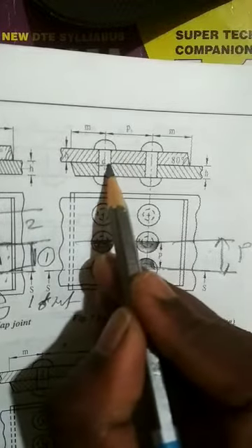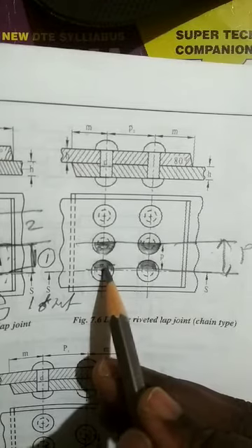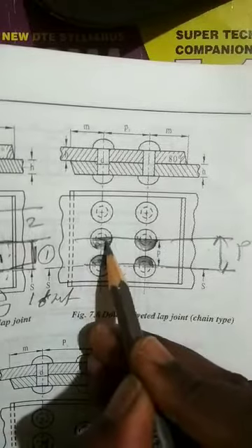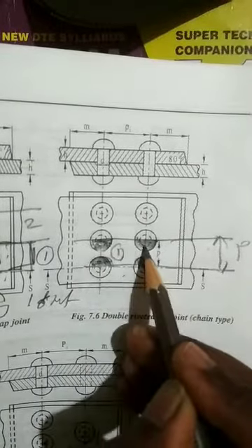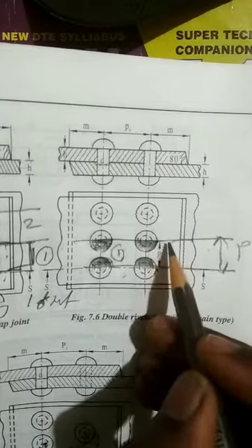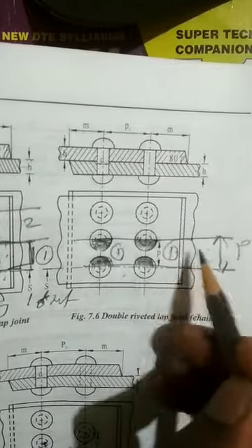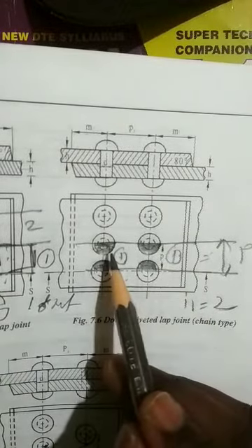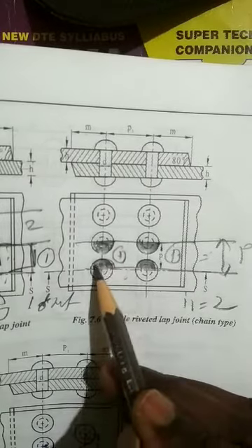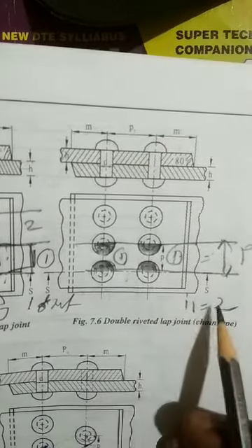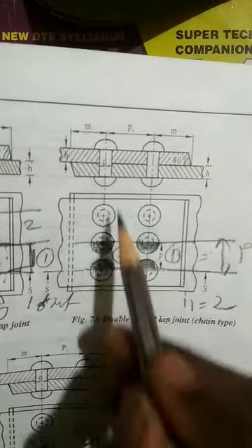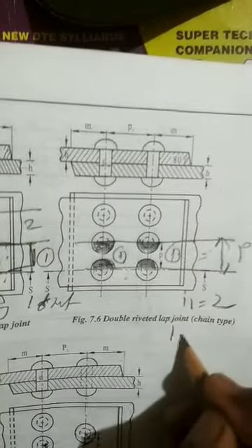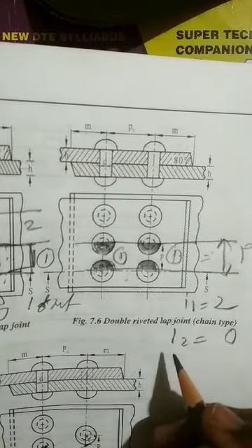Only a single cut may occur here. Then you have to find the number of rivets in single shear per pitch length. In one pitch, how many? This half and this half will join to make one rivet. This and this half will join to form another rivet. Then 1 plus 1 is equal to 2. Then I1 is equal to 2. I1 is the number of rivets in single shear. This half and this half will make a 1. So this is also 1. 1 plus 1 is equal to 2. Then for a double riveted lap joint, the number of rivets in single shear is equal to 2. What about I2? It is equal to 0. Why? Because in the case of